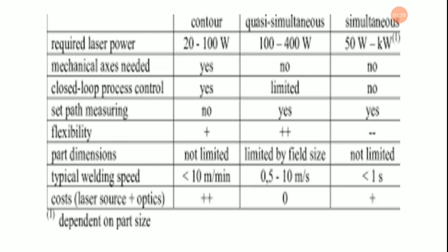Now, the selection of process parameters for obtaining optimal weld pool geometry in the AC pulse GTAW of A7075 T6 aluminum alloy is being analyzed. The traditional Taguchi method is widely used for optimizing the process parameters of a single response problem. Optimization of a single response results in non-optimum values for the remaining responses.